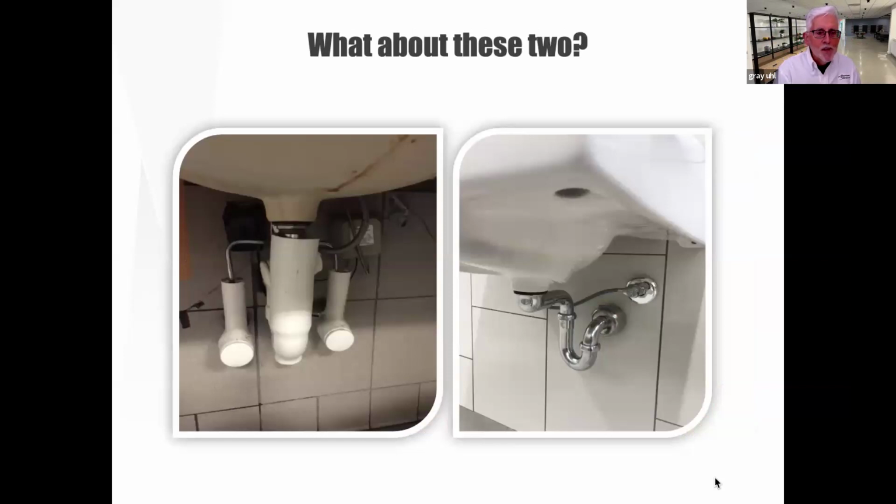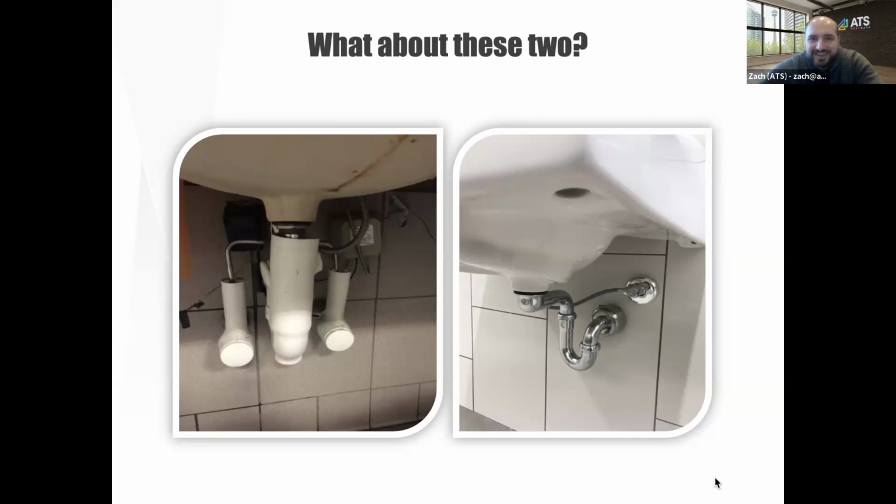So again, what do you think are the differences between these two under sink installations? There's a lot, actually. This one's a fair bit. It'll give the crowd some chance to look at it before I start saying some. I think the obvious one is the insulation cover for barrier-free code. Yep, they put the covers on, and that is for barrier-free. That's right, so your knees don't get burned. The stops in the drain. The glazed underside of the bowl. Yeah, that's a good one. Yeah, excellent.